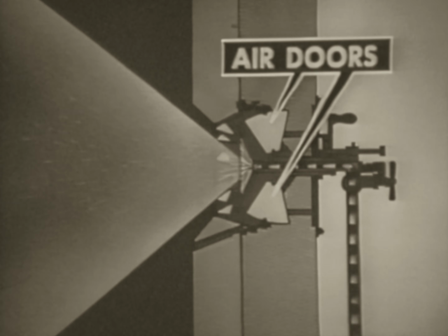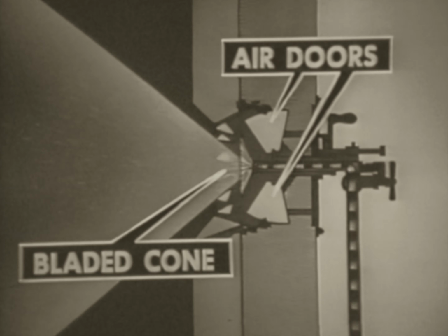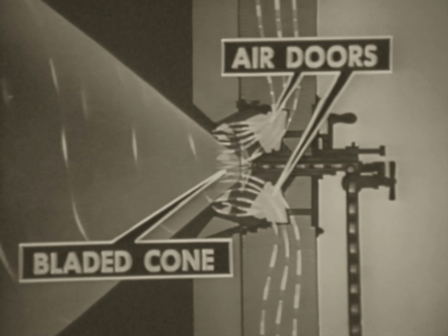Then the air doors and the bladed cone in the burner register mix these particles with air to form the combustible mixture. Although all burners perform these two functions, atomizing the oil and mixing it with air, different types of burners atomize the oil in different ways.